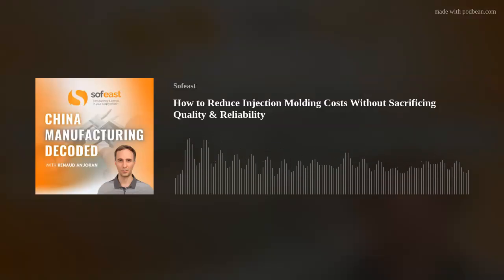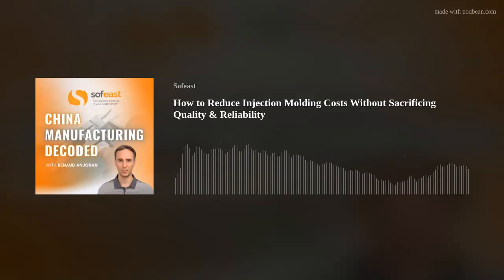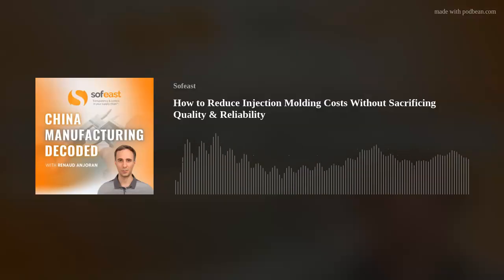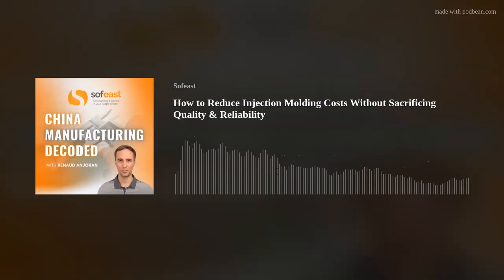The smaller the draft angle, the more problematic getting the molded part out of the tool. So the greater the draft angle, the easier the tool runs. Therefore, it's more efficient, and your yield rate is going to be higher. Instead of having a really tight draft angle, which is more problematic, you're going to get more scrap.